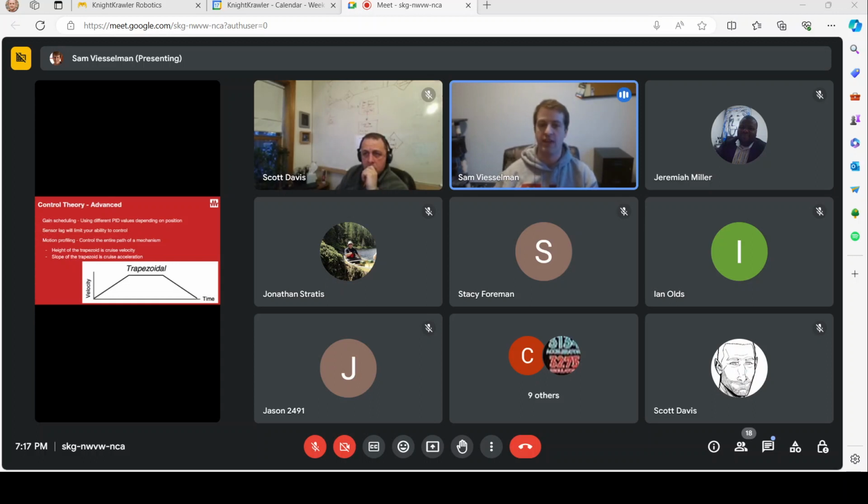The other one that is really laggy, that a lot of teams I'm sure have run into, is when you're reading a vision target, because the camera has to take a picture, has to process the picture, has to send it over the network, and the RoboRio has to read it. So even aligning to a target, a lot of times you'll find it's very challenging to align using PID as fast as you'd like to, because there's this inherent lag effect. And really PID does not take into account that lag. There are other control forms that do, but there are also ways to take care of that with PID as well, to try to do your best.